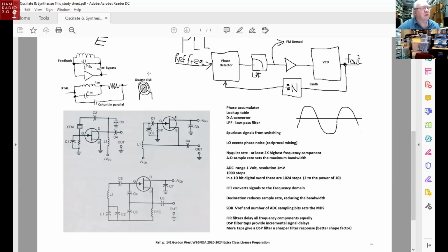What it is, it's a disc, kind of like a coin. A coin, a 10-cent dime, is a disc. And this disc is made out of quartz. It's called a quartz crystal. And how this works is there's a patch of metallization on each side so that you can put voltage across this disc. And there's a wire lead attached to it, so you can get it connected in your circuit.